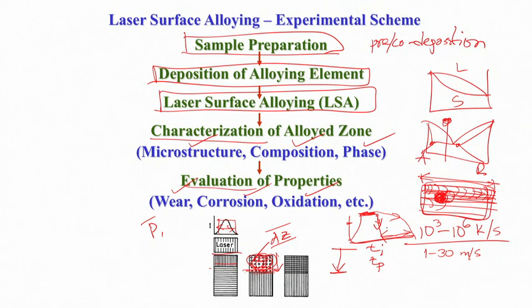Whereas in laser solidified surfaces, we end up getting at the most directionally grown columnar grains, and there may be a semblance of dendritic formation, but not necessarily long primary arms, only very short secondary arms. So in the process, compositional heterogeneity exists but is not very large.